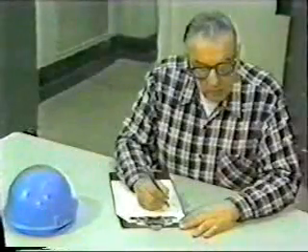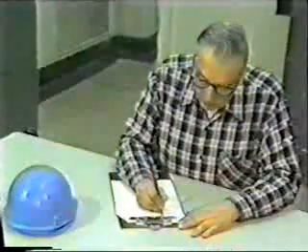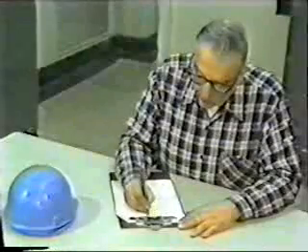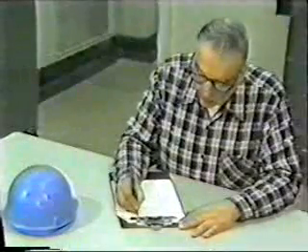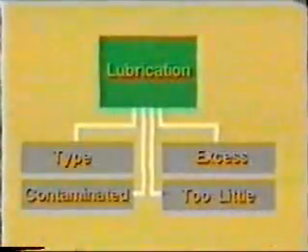Well, that completes this troubleshooting procedure. In the next segment, we'll start troubleshooting another centrifugal pump problem. But first, let's review. Normal operation requires proper alignment. Indications that alignment is proper include a lack of excessive vibration, only one bearing being affected, and a lack of effect on pump function. Normal bearing operation also requires proper lubrication.